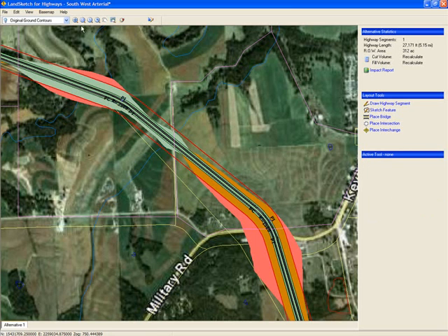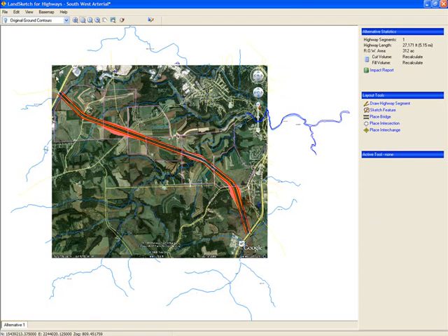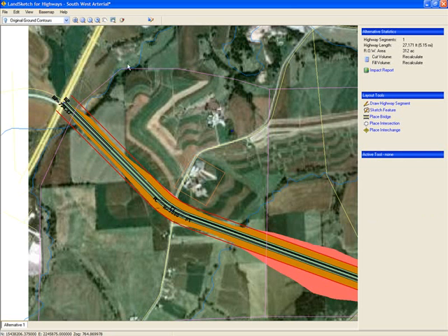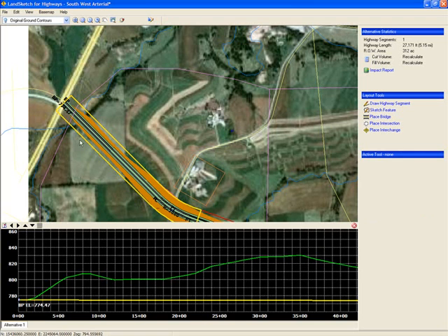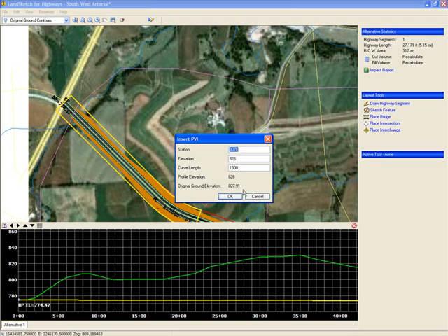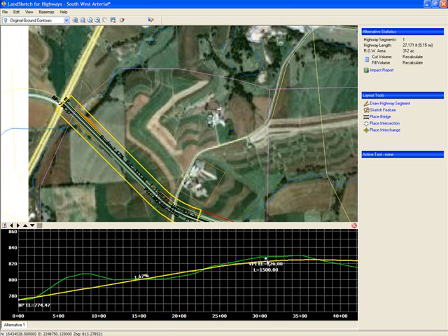Here you add the vertical curves at the desired locations visually using the yellow highlighted area in the plan view as a reference. Modifications to VPI locations and curve lengths can be made by dragging and editing the various profile elements. And like the adjustments in the plan view, any changes automatically update the corridor and impact report. Other visual cues help identify other potential concerns such as excessive cut or fill.